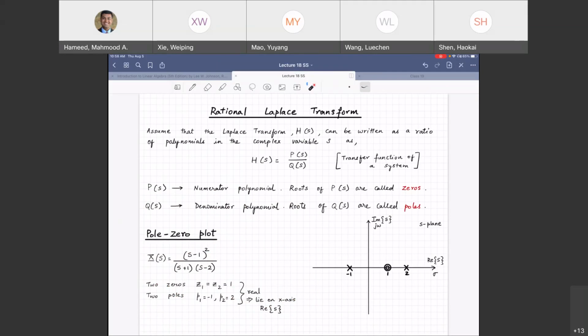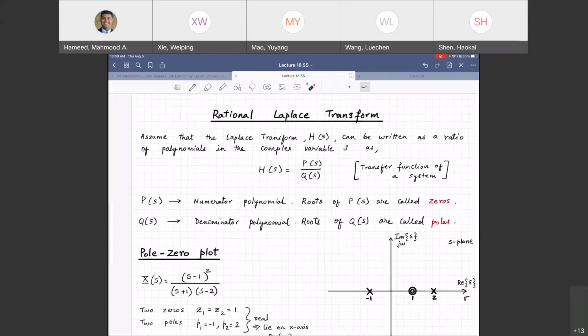If the poles of the transfer function of your system are in the left half of the S-plane, that indicates stable behavior. If you are in the right half, that is unstable behavior. So by just looking at the location of the poles, you can find that out. But is there math that supports that statement? Let's try to look at that. The initial part of the slide over here, you have seen before.